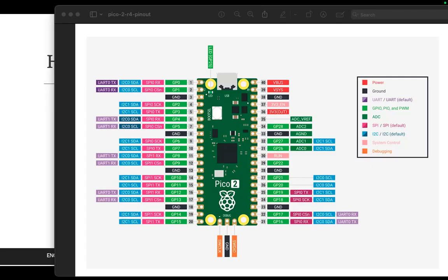What do you need when you try to connect a sensor or other devices? You need to decide which communication protocol you need to use. For our lab, you don't need to worry about these things. But for the final project, we want to connect sensors and other devices, so you need to choose the proper communication protocol. Any questions so far? If you want speed, the SPI is very fast. If you want fewer wires, you can choose the I2C. If you want simplicity, you can choose the UART.